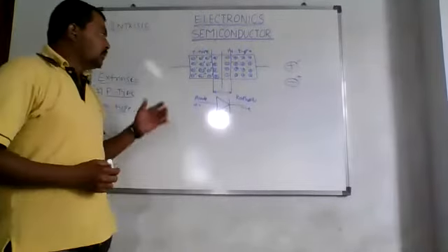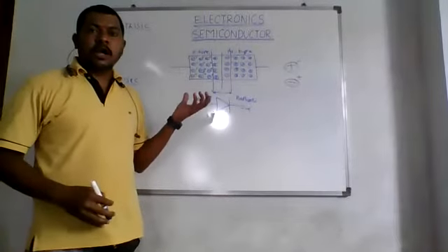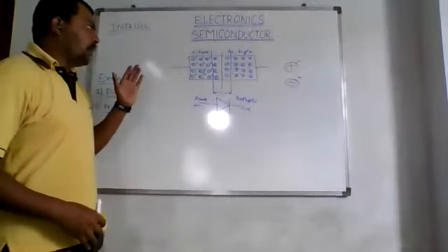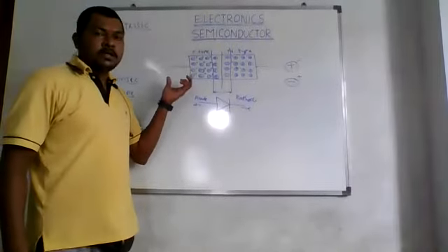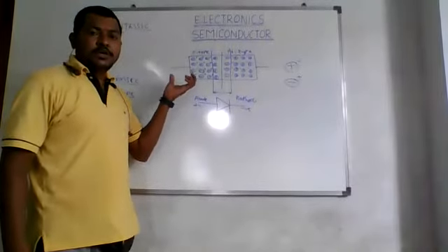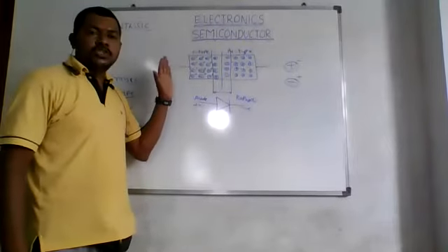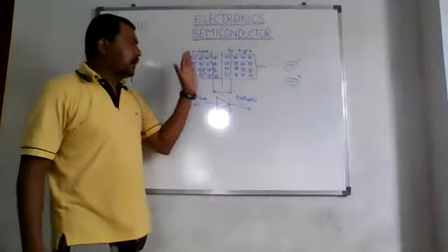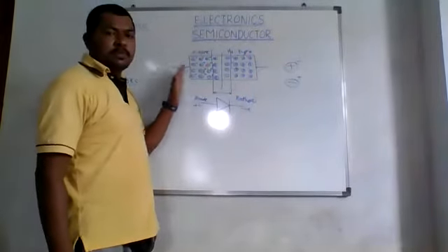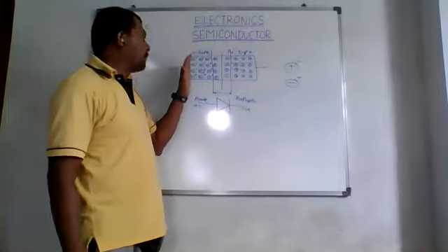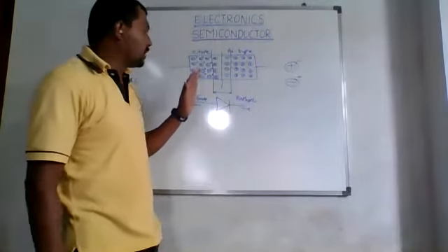In the last class, we studied the PN junction diode and how it is formed, right? What we studied yesterday, I will just repeat for you. When a single chip of pure intrinsic semiconductor is doped on half of the portion by a trivalent impurity and the other half by a pentavalent impurity, then one part will be a p type semiconductor. Similarly, on the other side we'll have an n type semiconductor.